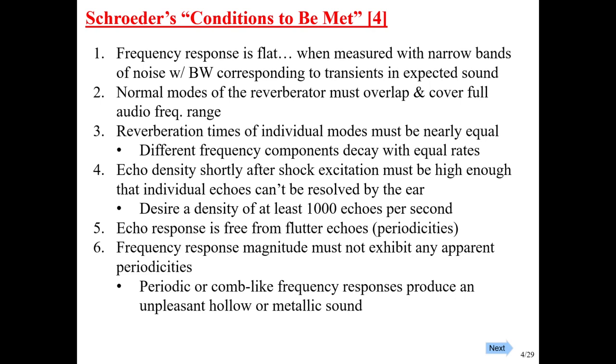And also he points out, we haven't really talked about this yet, that we also don't want periodic peaks in the frequency response, so along the f-axis. That would be like a comb filter. The reason we don't want that is people had tried those earlier, and they do give a reverb-like sound, but they sound very metallic or hollow.